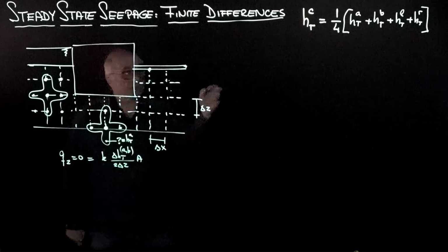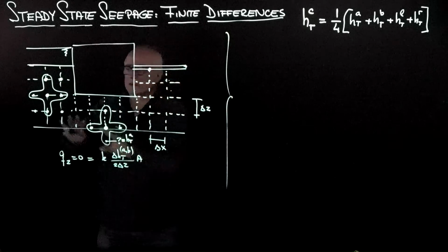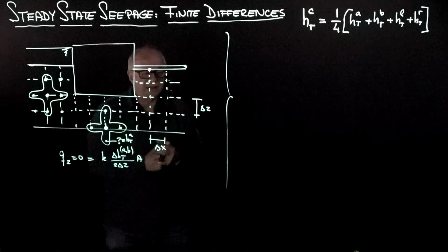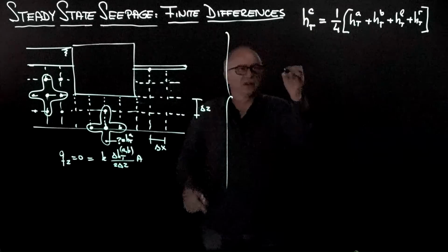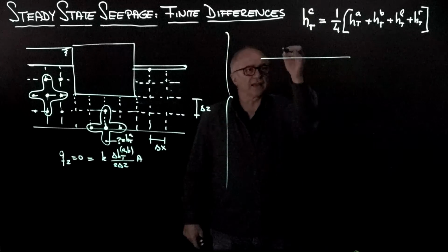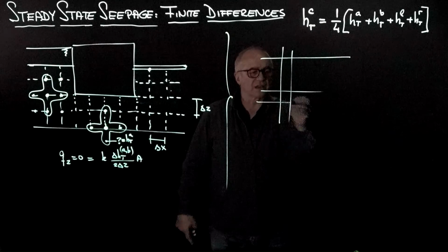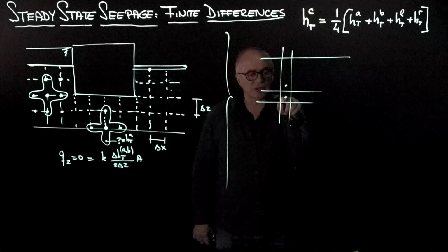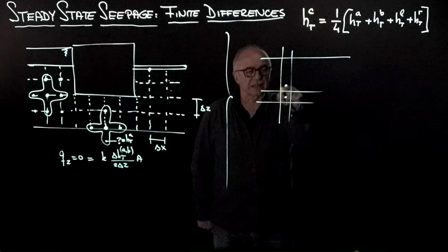And so finally, you can do this by successive iterations, moving the kernel in x and y throughout the system. But you can very easily do it in Excel, for example, where each cell in Excel is actually reproducing each of the nodes here. So you have an equation for each point. There is an equation here which tells you it is the average of the values to the left, to the right, above and below.